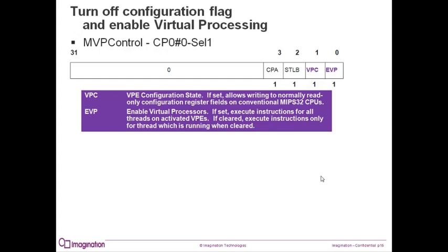Finally, to enable multi-threading and start all enabled threads executing, I need to turn off configuration mode and enable virtual processing. These are set in the MVP control register.